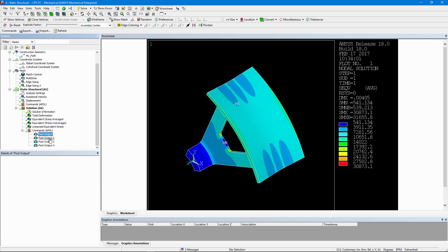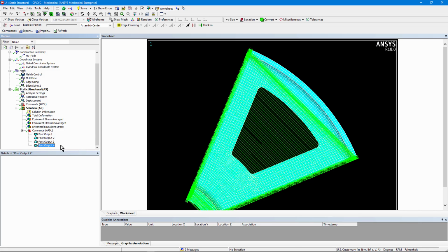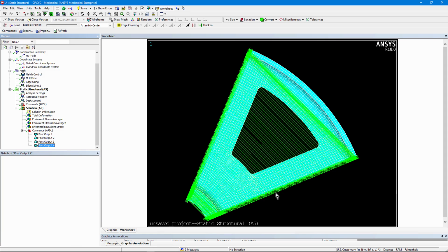There's the model. There it is without averaging. There's a view of the elements with the nodal coupling, and it's more easily seen directly from the front. You can see that the nodes have been coupled. Those nodes found 45 degrees apart, and if you see the direction these little triangles point, you can see that the nodes have been rotated 45 degrees, so that tangential movement here is coupled with tangential movement here with a 45-degree change in the direction in the cylindrical Y or tangential direction.